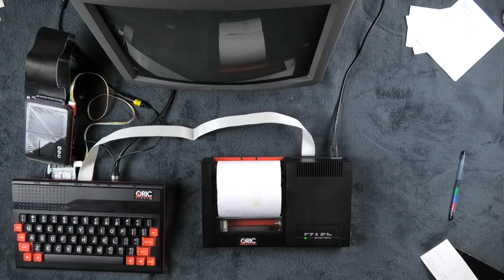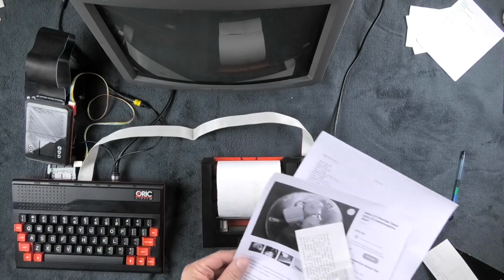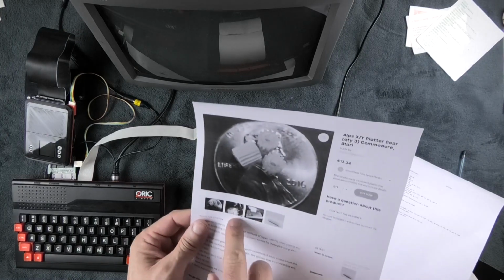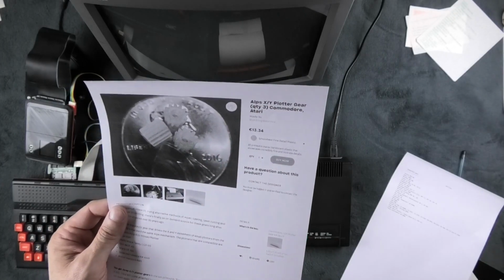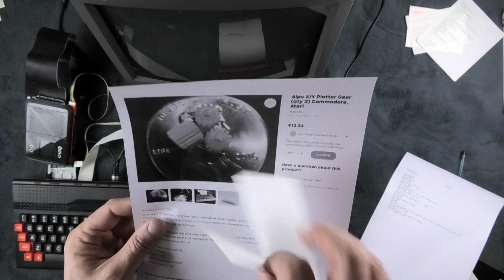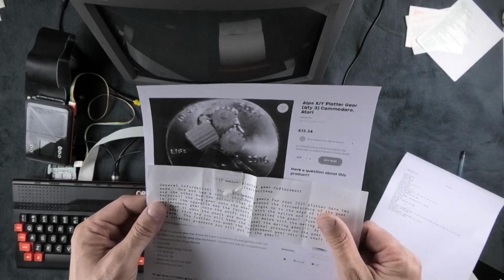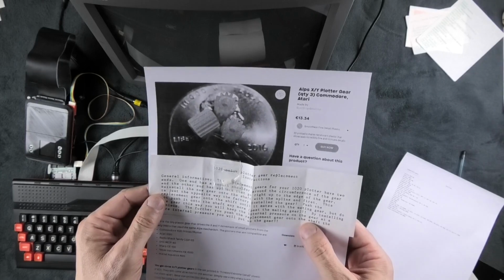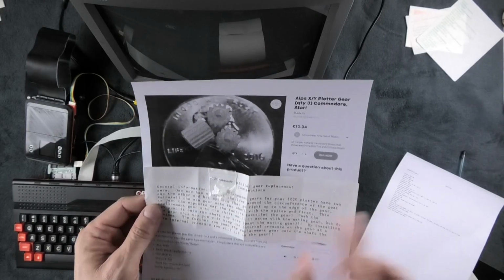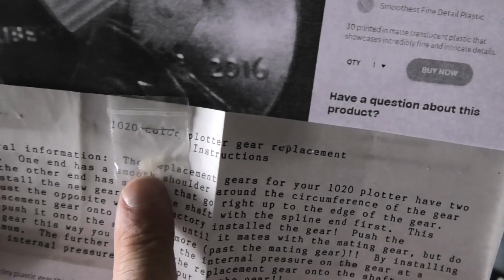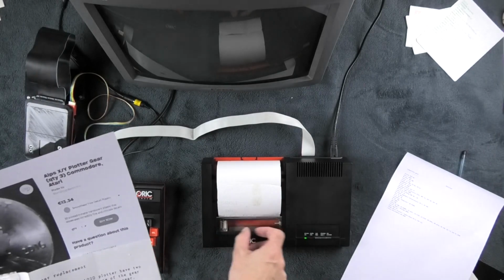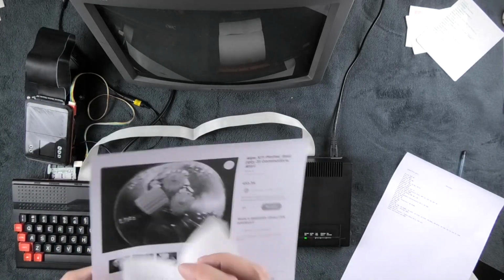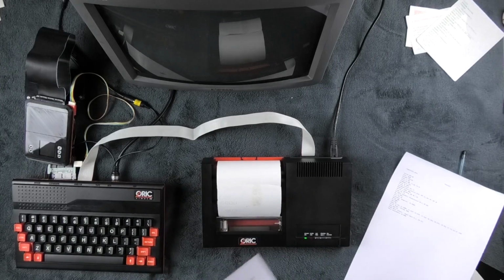So I was talking about the consumables. The typical failure is these small gears here. So you can find now some people are making them using 3D printing, but you can also find some new old stock, like that one which I got from an American company, was it Best Electronics? And you can see that these things are very tiny. And basically it happens when people are trying to move things violently, or when there is a bad bump, so highly not recommended.